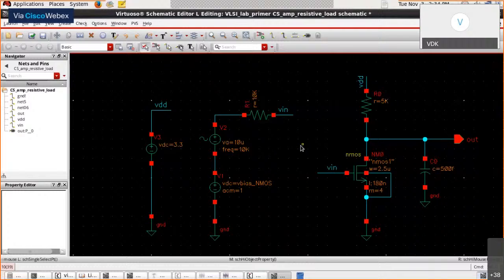The first analysis we run is the DC operating point analysis to check, first of all, whether the MOSFET is indeed operating in its saturation region in the ID-VDS plane. Because if it is not, then it is not working as a voltage controlled current source. First check is that region of operation. Then we check all other small signal parameters available from this particular MOSFET for this size and the biasing that we have computed. Is that fine? So let us go ahead to the simulation setup.